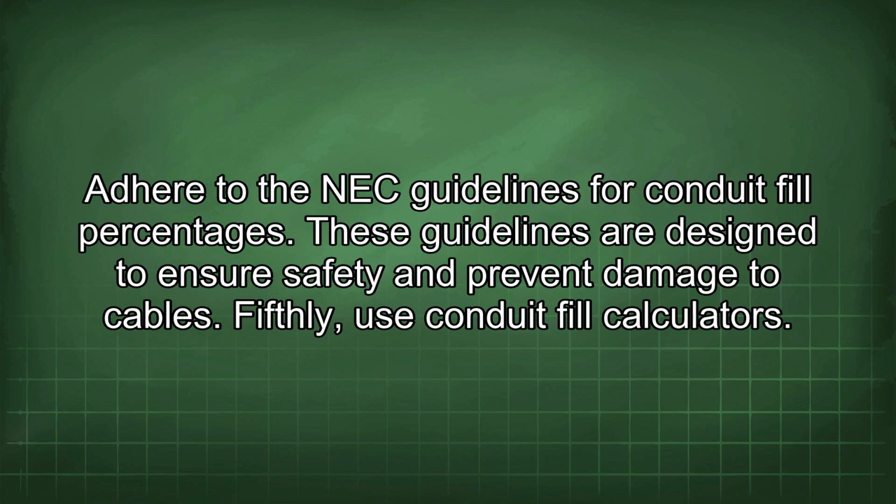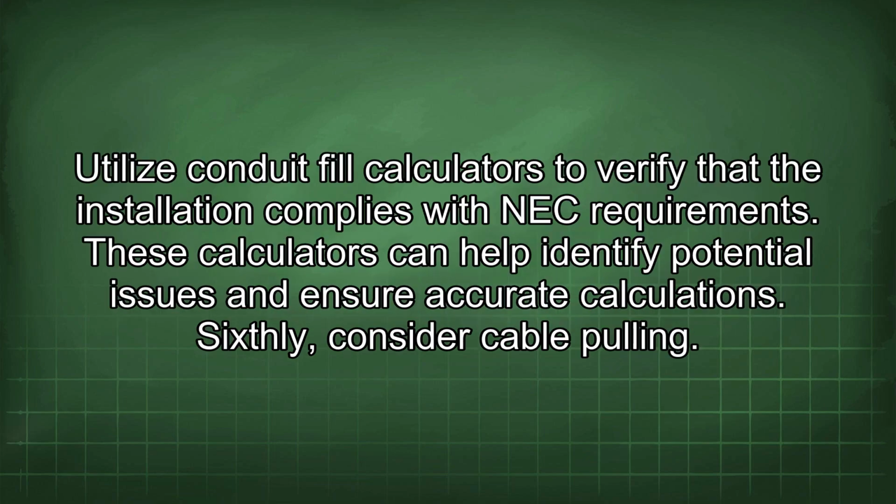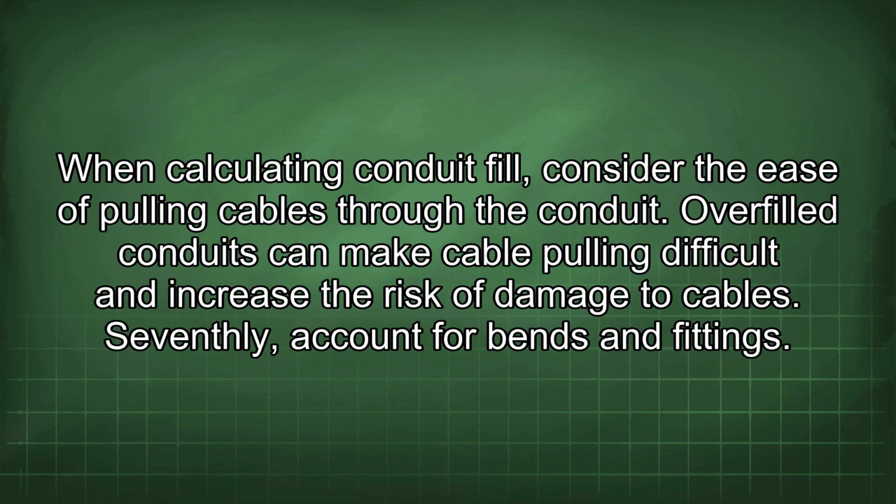Fifthly, use conduit fill calculators. Utilize conduit fill calculators to verify that the installation complies with NEC requirements. These calculators can help identify potential issues and ensure accurate calculations. Sixthly, consider cable pulling. When calculating conduit fill, consider the ease of pulling cables through the conduit. Overfilled conduits can make cable pulling difficult and increase the risk of damage to cables.